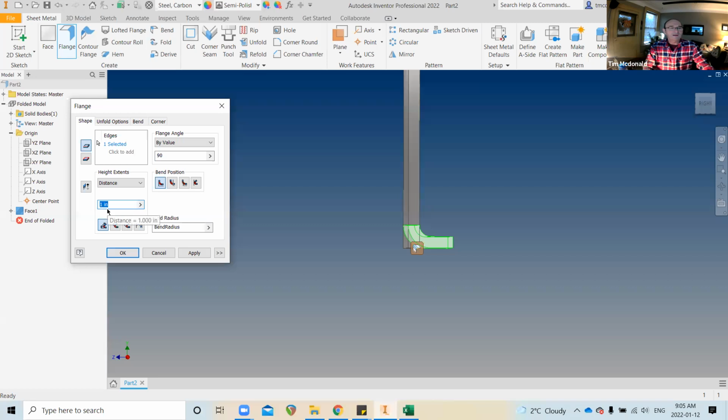I'm going to change this value from 4 to 3. I like 3. Okay, and I'm going to call this leg. Again, a dynamic input box, whether it is a dimension on a sketch or one of the input boxes in your panels here. I'm just going to put leg equals 3. So I can create my parameter names as I go along.